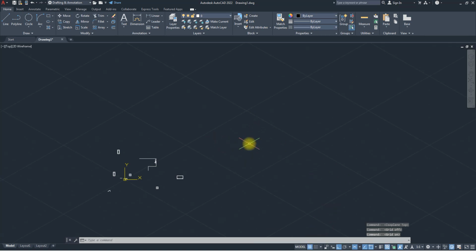So now it's not a question per se, it's more of a concern: every time I want to switch, I have to come here and switch. I want to draw this, I have to come here again and switch. This is time consuming. There's a shortcut. Please, this shortcut is important if you want your work to be fast. The shortcut for switching between different views is F5.